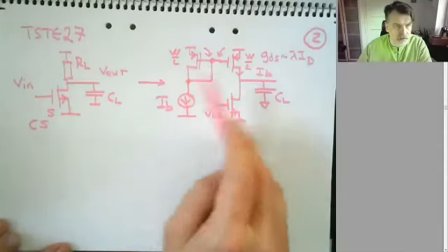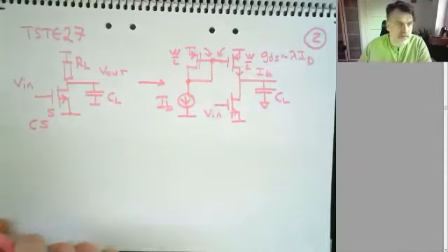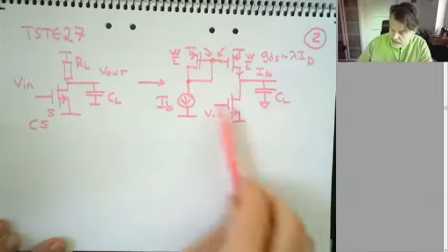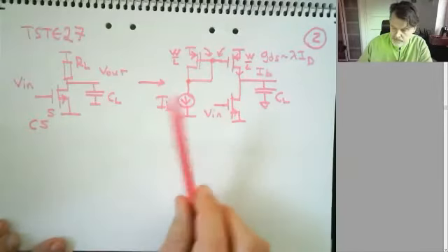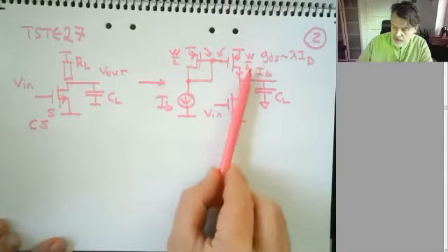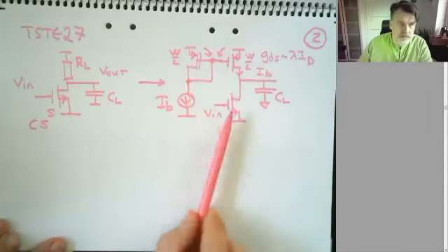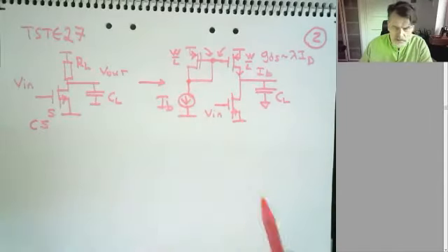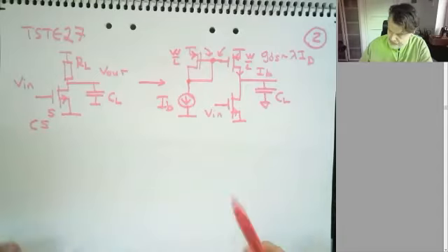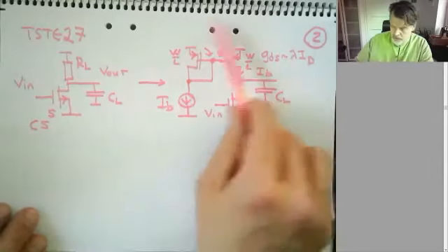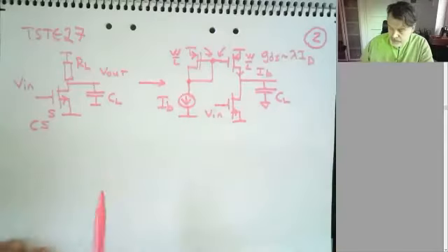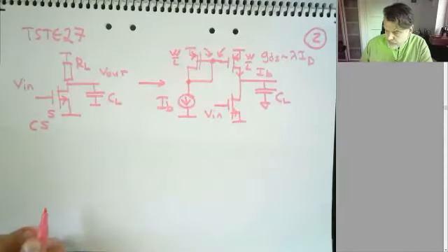So that's the elegant way of getting rid of design parameters. I don't really have to care about these two transistors. Otherwise, I would get a huge design space: W/L, W/L, VGS, VGS, current, etc. That would give me an additional 6-7 parameters. So that's a practical way of doing it.